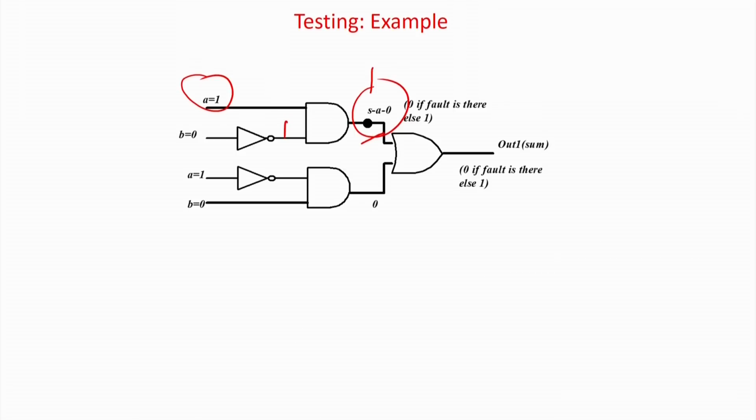We will be dealing with this in detail, because we have a full module with 6 lectures on testing, where we will see how this is a more optimized implementation in comparison to exhaustive testing. In this case, if there are 4 input lines, all possible patterns will be 2 to the power 4. But if you have a very large circuit with 100 inputs, all possible input patterns will be 2 to the power 100. There is no question of doing it.